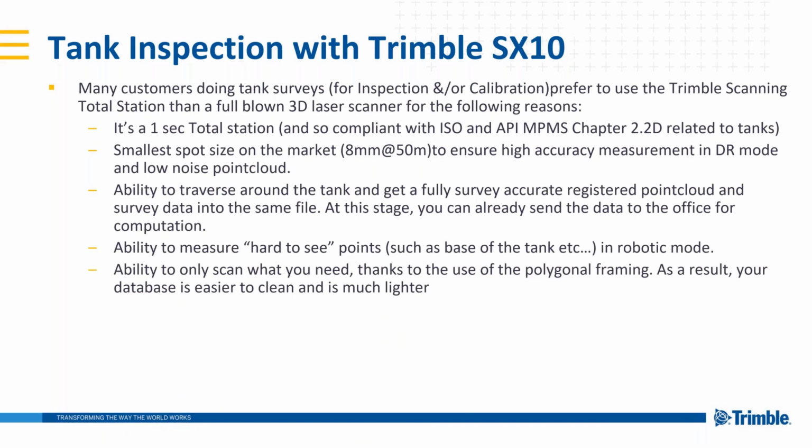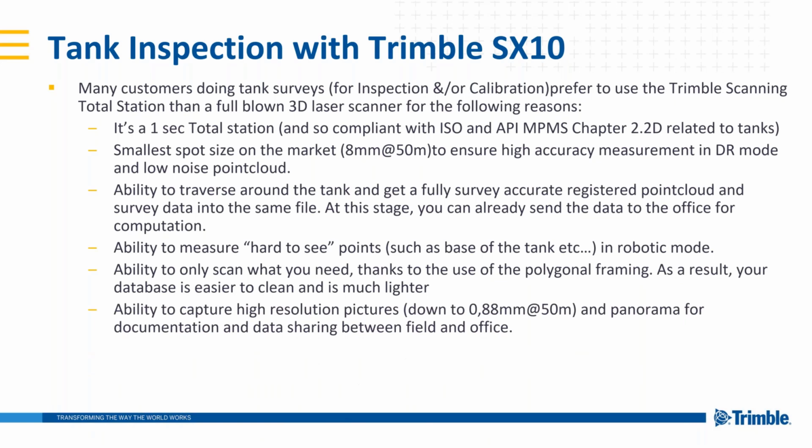And it also has the ability to only scan what you need because you're using a survey traverse to register all of your stations together. You don't have to rely on overlapping point cloud data, which means that you can scan small areas. So even though it doesn't have the high speed of what we would refer to as a full-blown laser scanner, you do get some time savings in that you can scan small areas.